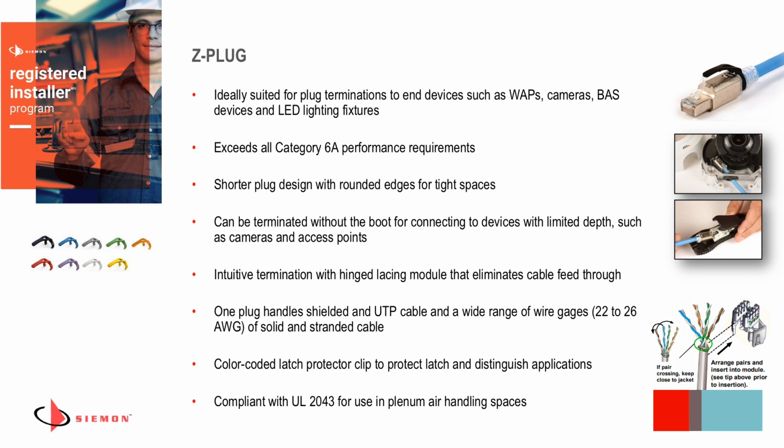The nice part about these plugs is it's not a legacy style plug where you're trying to feed conductors in through tiny slots, which is difficult when making sure you get the color codes right. This actually laces and terminates very similar to a ZMAX module, in that you just insert a cable, follow a color code, and then trim them and insert it into the Z-Plug termination tool. So it's a fairly easy termination process, and certainly much easier than legacy plugs.